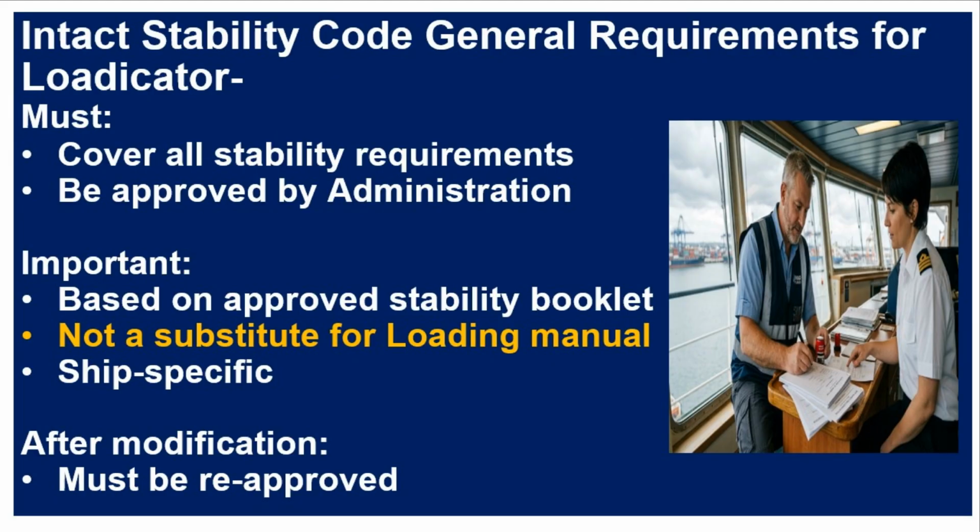Intact Stability Code, general requirements for Loadicator. Must cover all stability requirements. Be approved by the administration. Important. Based on the approved stability booklet. Not a substitute for the loading manual. Ship-specific. After modification, must be reapproved.